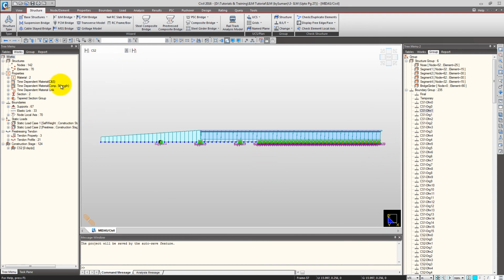All the boundary conditions would be here. So you can anytime later on change any of the parameters like the boundary conditions or any loads which are coming onto CS2. You can apply them after running the wizard. So I'll go to CS21. So from there the incremental pushing would start. So the pushing would be done till the 30 meters.